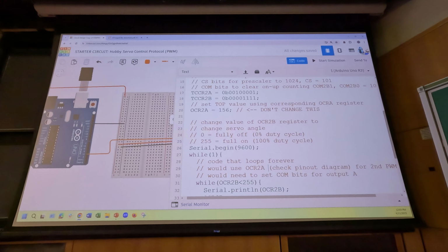Hold on, I'm sorry, give me 1 second. I had the values somewhere. So I have values of 3 and 21 written down, which is a little outside of the range. 21 winds up giving you, I think, a 2.6 millisecond pulse. So again, 1 to 2 milliseconds is kind of a nominal thing. Some of them you can actually push outside that and it'll go a little farther. It's going to depend on the exact servo. I believe this should work for these.